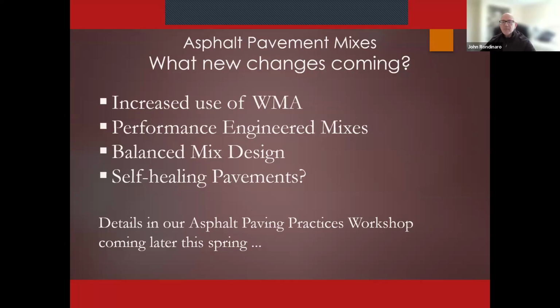We're going to start to see performance engineered mixes, where you're picking different performance criteria, such as cracking and rutting resistance, and you're going to be engineering your mix specific to address those distresses. Balanced mix design is taking performance engineered mixes that next step further, where you are actually balancing out your cracking resistance and your rutting resistance.